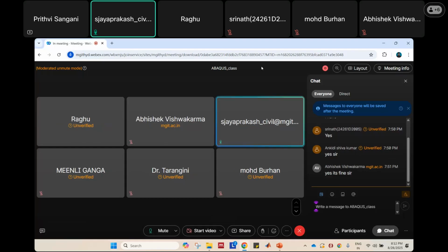Yeah, Prithvi, actually, when we are doing the plate load test, we have kept the load which is equivalent to the axial load on the box girder. But coming to the earth pressure, earth is there and it undergoes some pressure. Have you considered the surcharge effect? Because in the design, generally we consider the surcharge, but when you are doing the plate load, have you taken any surcharge additionally?